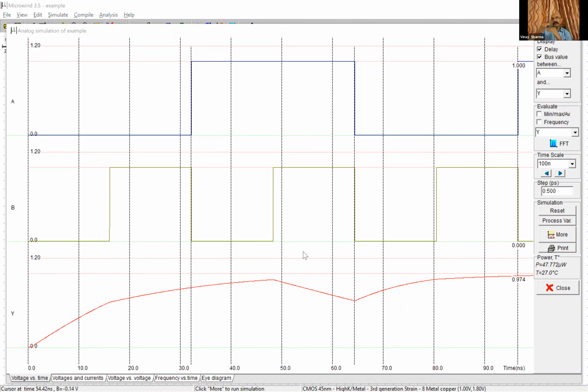So as there were metal layers 1, 2, 3, 4, 5, 6, I mean like 6 metal layers on top of each other, and big IO pads, as you know, compared to the size of the NAND gate you're using, they're so stacked. So it's not able to drive it. Okay. It simply cannot. And then your design will be a disaster. Okay. So they won't work. They work on the simulations, but as you connect IO pads, things become complicated.